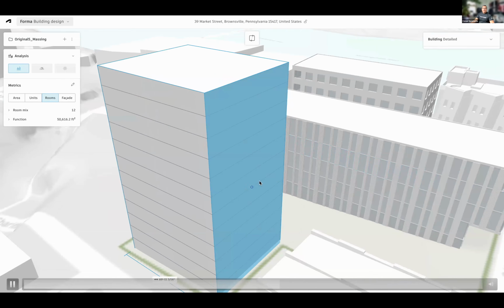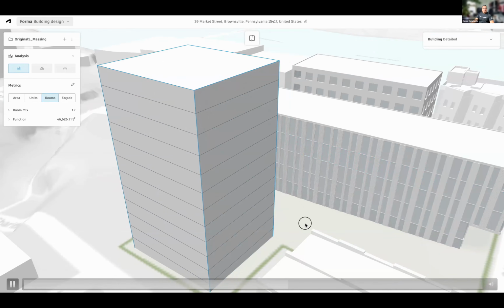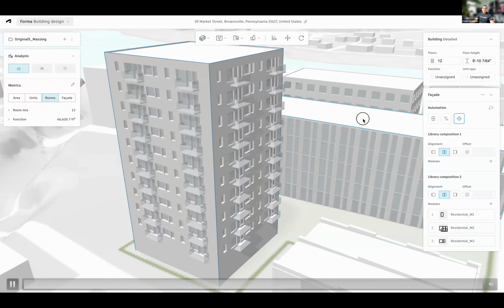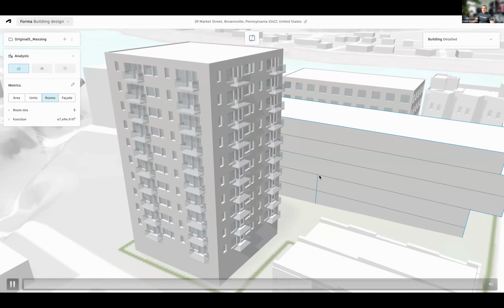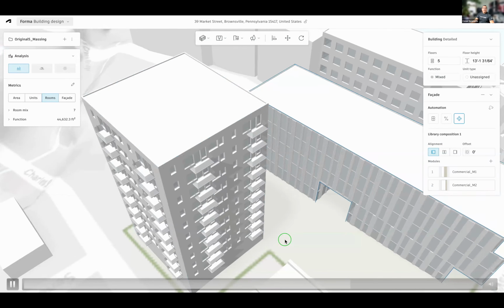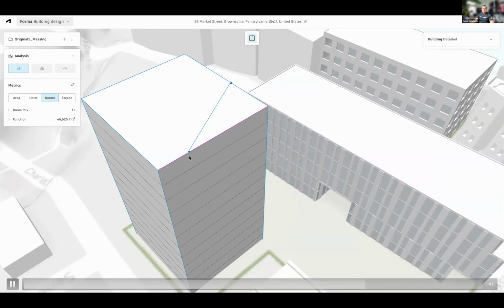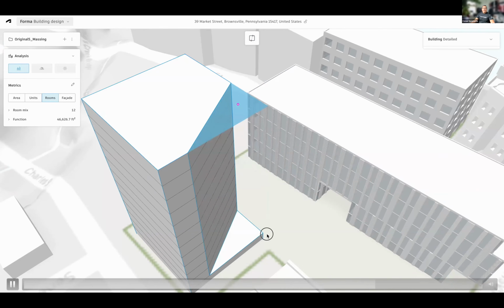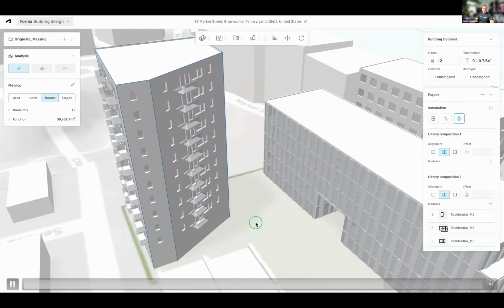I added a second building. This is a little taller with residential typology. And I can modify multiple facades, tweaking heights, and begin building a more varied composition. And if you need to change the envelope, you can apply different facade modules to reset the default module